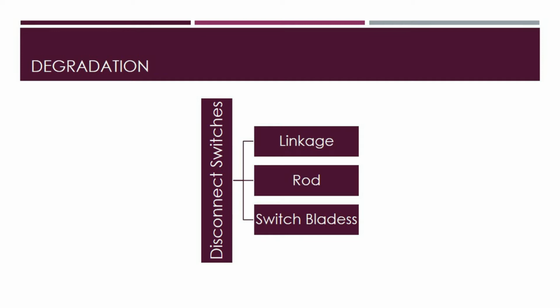Corrosion around the mechanical linkages of these switches is common, and it can cause the switch to stop working. The switch functioning mechanism may cease if the lubricant dries up, rendering the disconnect switch useless. Air pollution, albeit a less common mode of degradation, can also impair the support of the insulators. And this is most common in heavily industrialized areas or locations where road de-icing salt is usually utilized.